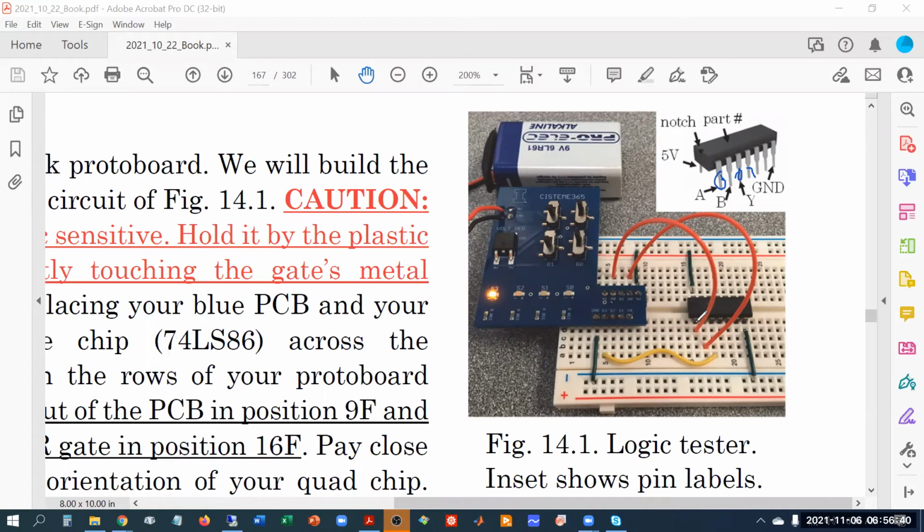And occasionally you'll have to measure voltages. To check that the inputs are doing what they're supposed to do, you can measure by connecting one of your digital multimeters, the black leg of the digital multimeter. We wrapped it around a wire and then plugged the wire into the breadboard. So we're measuring everything relative to ground. Some of the things we just checked: when we touch the digital multimeter to 5 volts, we get 5 volts. We touch each one of these switches one at a time, and we switch these on and off, and we see, do we get from 0 to 5 volts showing up on the switches? If so, the switches are operating correctly.